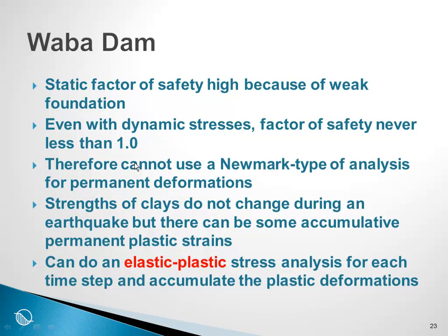So what we can do is use the quake results in SIGMA, and we can do an elastic plastic stress analysis in SIGMA for each time step and accumulate the plastic deformation. Conceptually, when we do an elastic plastic deformation analysis, we might have some elastic deformation and then some plastic deformation.